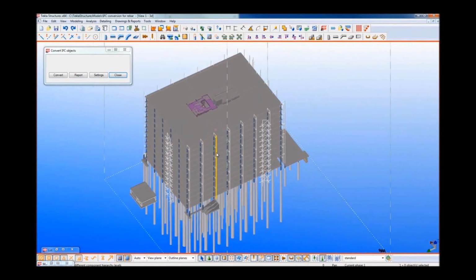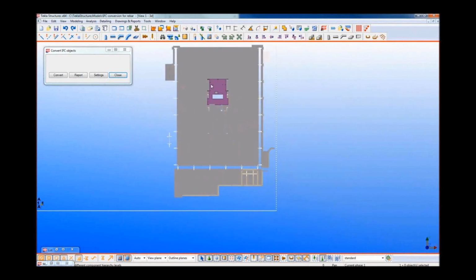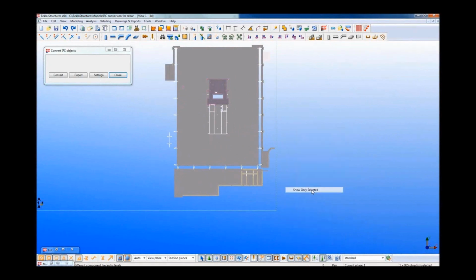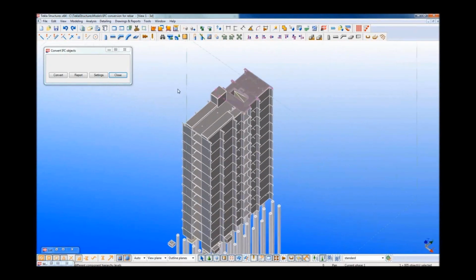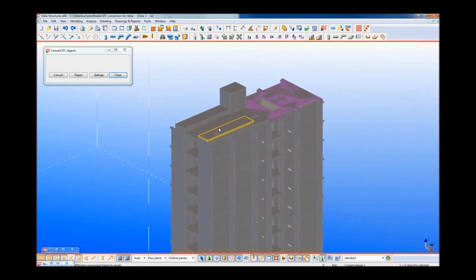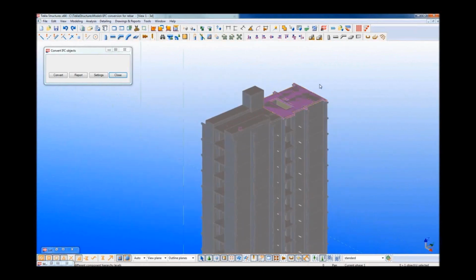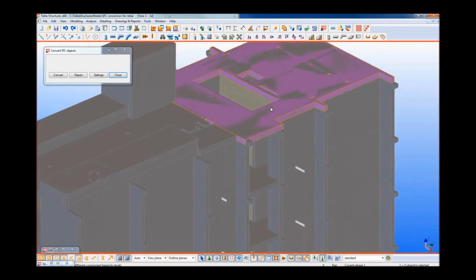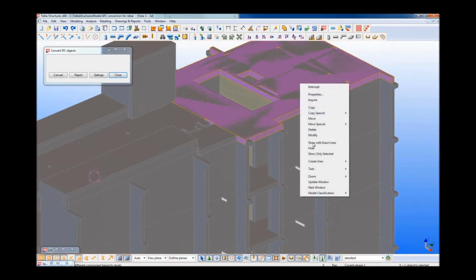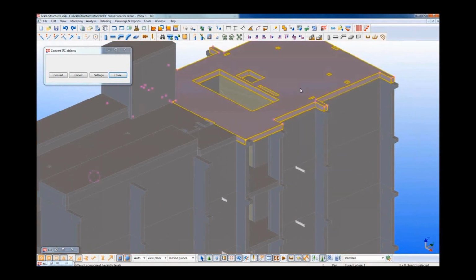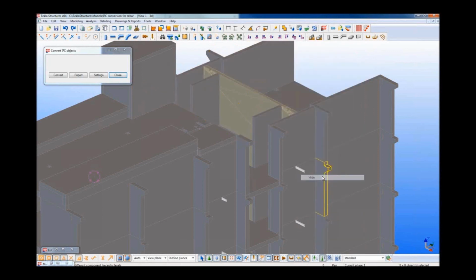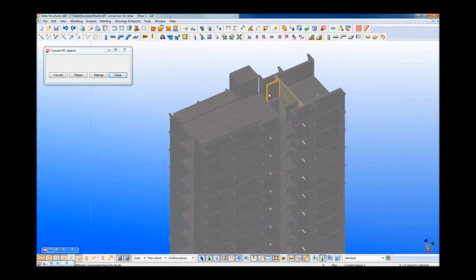You can also bulk edit. If I go and let's just pick the car. So just going to get the concrete car, which is effectively the cast in place part on this. We've got foundations as well, but we'll just focus on the car for now. Let's hide the Tekla and the slab we've already converted.